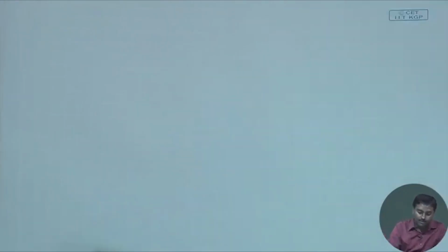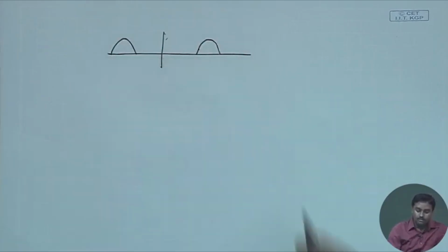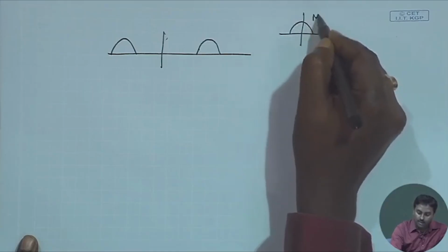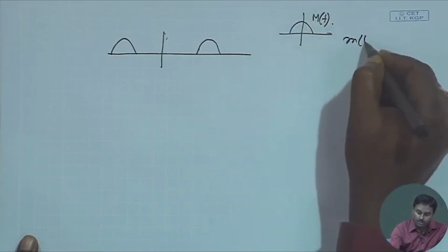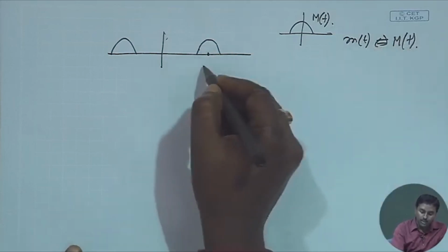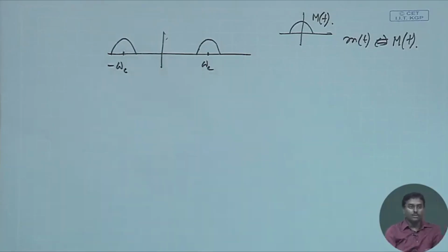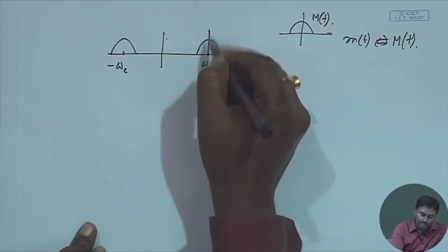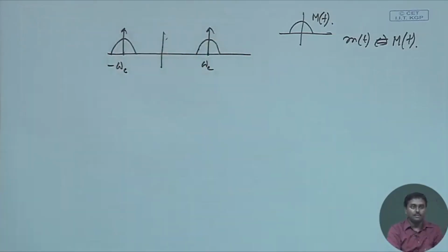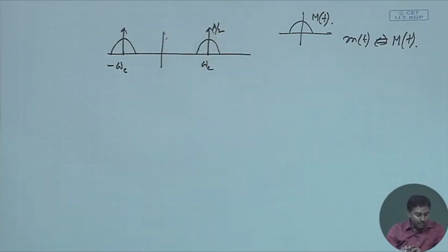Okay. So, if I have just a general modulated signal, so that the m t has a Fourier transform of M f, let us say. So, if I modulate that with omega c, that should be my representation if I do DSB-SC. If I add carrier, there should be just a delta function at omega c, okay, of strength a by 2, of course. Fine. So, this is what we have told, and this is just a tone modulation version of that.